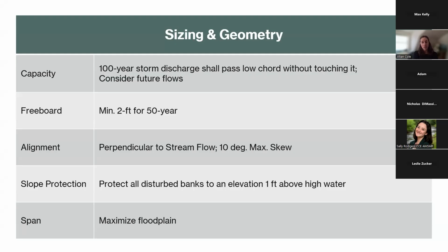And the span requirement for the bridge manual is based on capacity and required structure depth, but should really incorporate the floodplain to the greatest extent feasible, which is often limited by cost. But the DEC recommends at least 1.2 times the bankfull width or the average channel width.